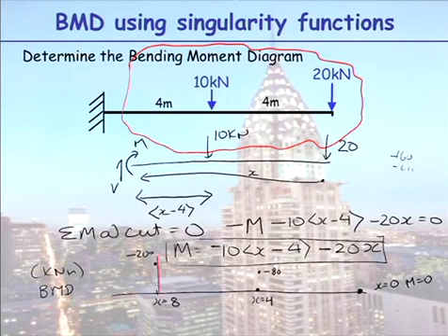So my bending moment diagram, oh, I'm doing a really bad drawing here. It looks like that. In this region here, M is equal to minus 20x. Now I have a moment here equal to minus 200. Guess what this reaction moment here is equal to? It's equal to 200. Because the moment in the beam is equal and opposite to the reaction moment.